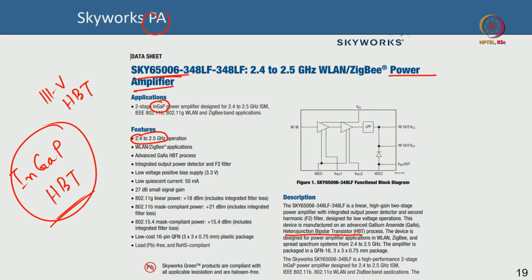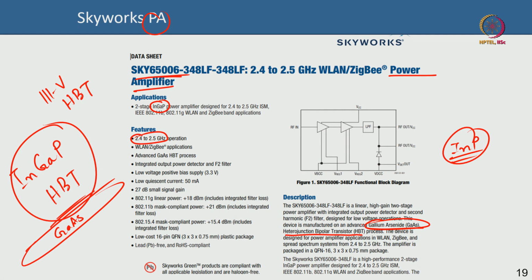So, indium gallium phosphide, this technology is built on the substrate which is gallium arsenide. That is why it is called gallium arsenide. There could also be an indium phosphide substrate that is a little bit more expensive. People might use it for military, strategic applications, where cost may not matter so much, but in things like this, of course in an iPhone also cost should not matter as much, but indium phosphide is more high performance, more niche, sub terahertz, it can go up to almost terahertz. But a gallium arsenide substrate is well enough to make an indium gallium phosphide device.